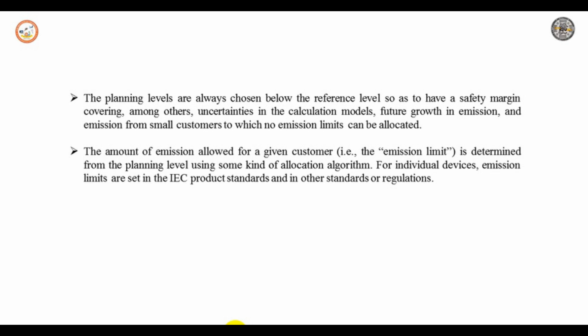The same will occur if the reference level for the distortion above 2 kHz is exploited for the one below 2 kHz. In fact, more and more consumer electronics and lighting equipment also generate interharmonics and high frequency harmonics. Also for triple harmonics, the disturbance level now exceeds or comes close to the reference value. In many cases,